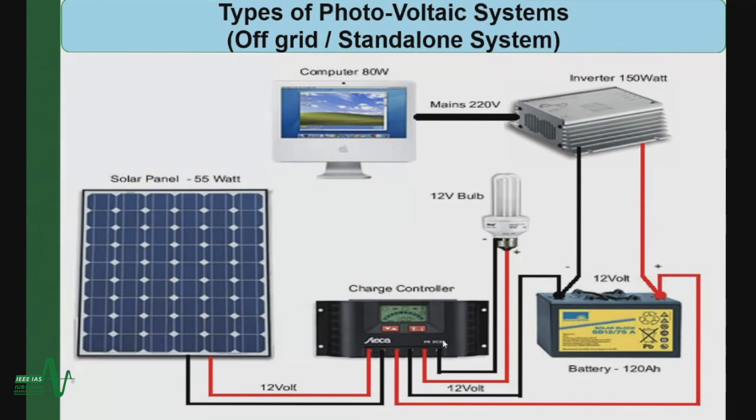So what is the charge controller? The charge controller is just a buck boost converter, nothing else. Whenever, let's say, the input voltage is 12 volt and your battery is also 12 volt, it slightly increases it, let's say to 14 volts, so that the battery section will get charged. And whenever the input voltage is lower than that, let's say 8 volts, the boost converter mode will be activated, and it will increase the value to, let's say, 14 volt. So the main portion of the charge controller is just the buck boost converter system.